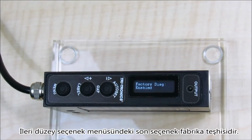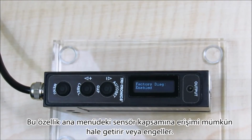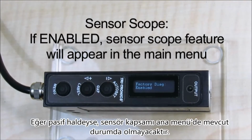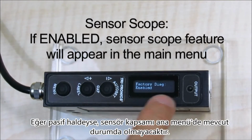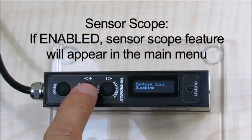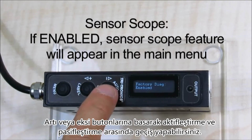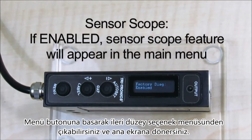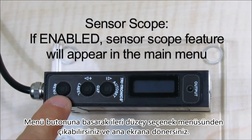The last option in the Advanced Options menu is Factory Diagnostic. This enables or disables access to the sensor scope feature in the main menu. If disabled, the sensor scope will not be available in the main menu. Toggle between enable and disable by tapping the plus or minus button. Tapping the menu button will exit out of the Advanced Options menu and back to the main screen.